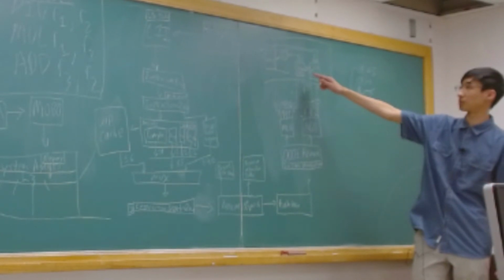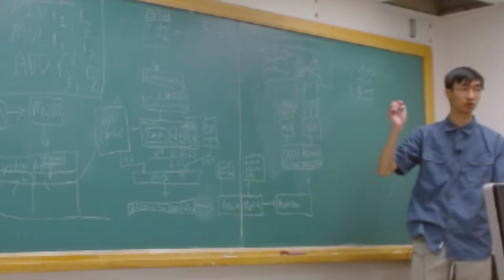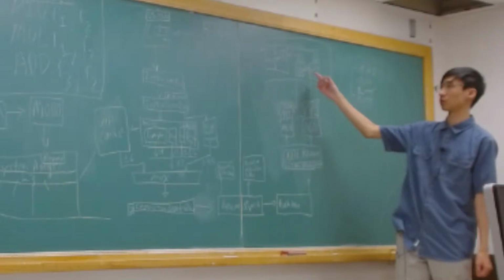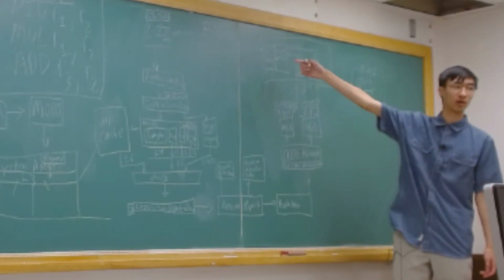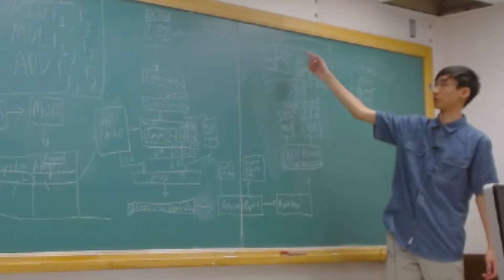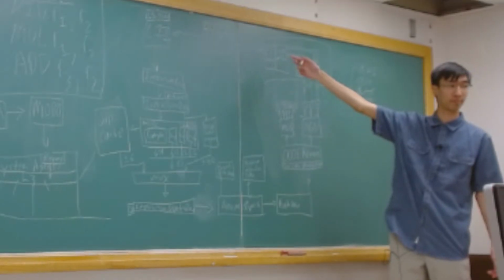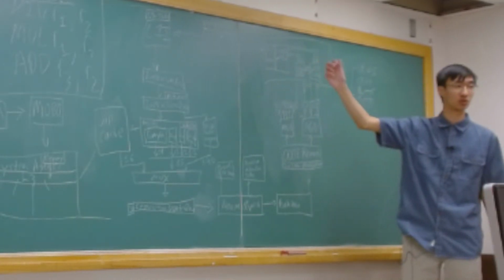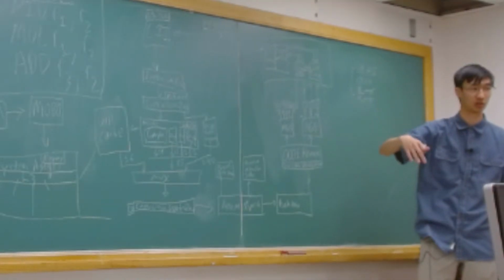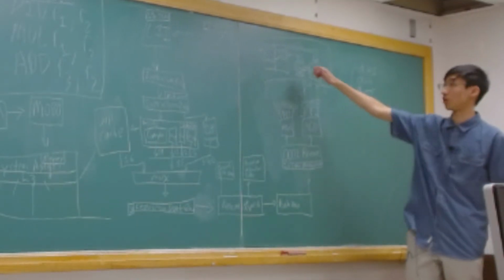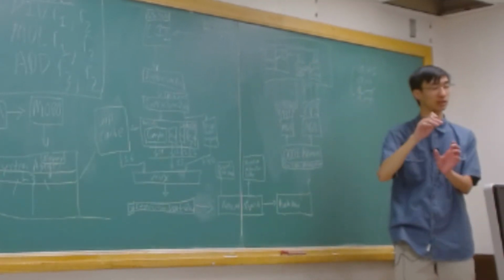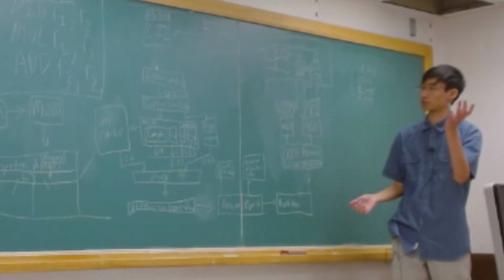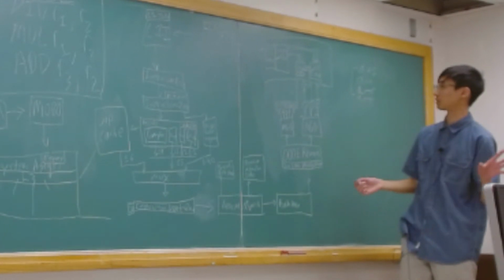Another thing to know is sometimes the store buffer is split into two. AMD did that on Zen 4 when they said we can do a buffer for storing where the store is going out to L1, and we can do a buffer for when it's coming back. So before we retire the instruction, before we say we're done, we'll also track those separately, and we can have a much larger amount of those running. That's an optimization AMD did, but that doesn't matter too much.